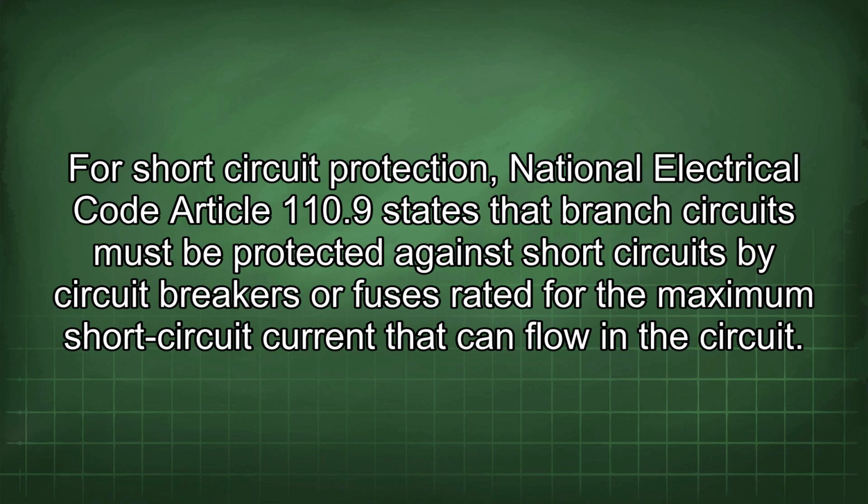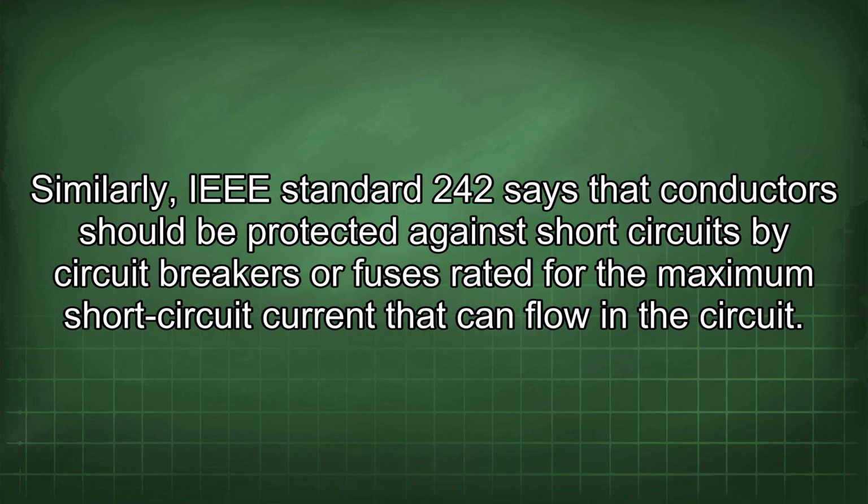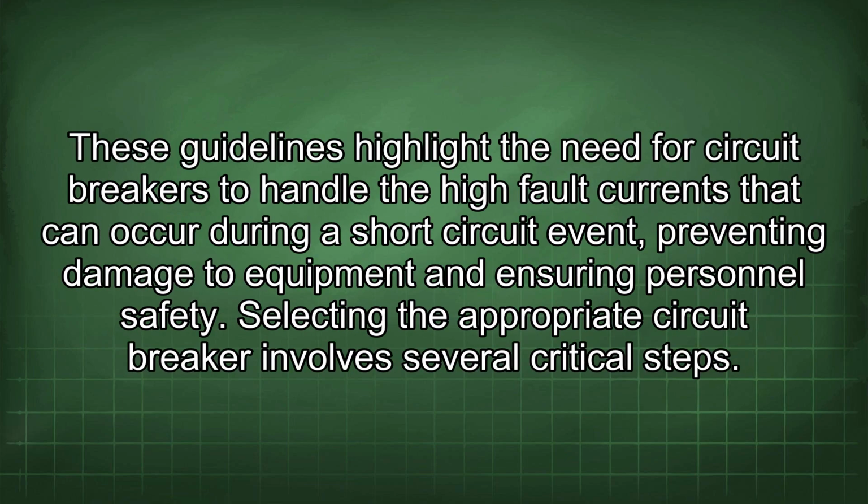by circuit breakers or fuses rated for the maximum short-circuit current that can flow in the circuit. Similarly, IEEE Standard 242 says that conductors should be protected against short circuits by circuit breakers or fuses rated for the maximum short-circuit current that can flow in the circuit. These guidelines highlight the need for circuit breakers to handle the high fault currents that can occur during a short-circuit event, preventing damage to equipment and ensuring personnel safety.